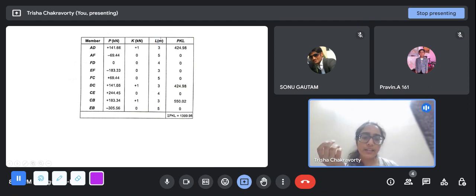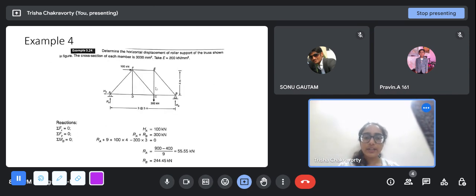And the lengths, again, you have to calculate from geometry. They won't all be given, okay? Because in civil engineering questions, generally redundant information is not given. Like if one side of a right angle triangle is given to be 3 and the other is 4, they won't write the other is 5. So the hypotenuse, you have to find that out. So the angle also won't be given. They will give you just the amount of information with which you can find out all the other information. So the lengths here, where this was given to be 3 and this was given to be 4, you know that this is also 4, these are 3, and all these hypotenuses are 5.